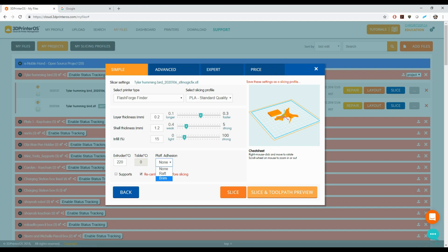And a brim is simply one layer projected out from your object, by about 5 millimeters. So if you had like a really thin stick or twig or lamppost or something that you're printing in a scene, you would use the brim because then it would give it some more stability when printing, less likely to knock it over as your print is going on.